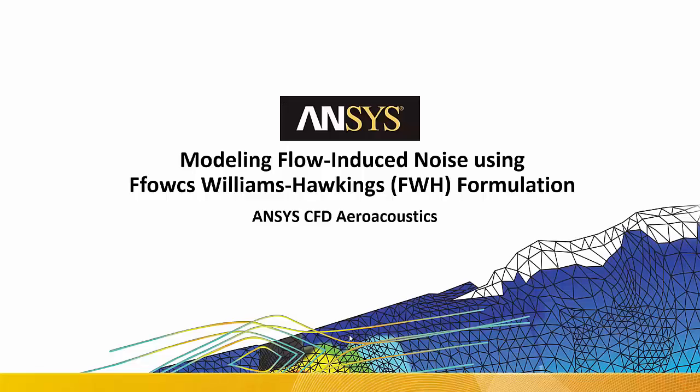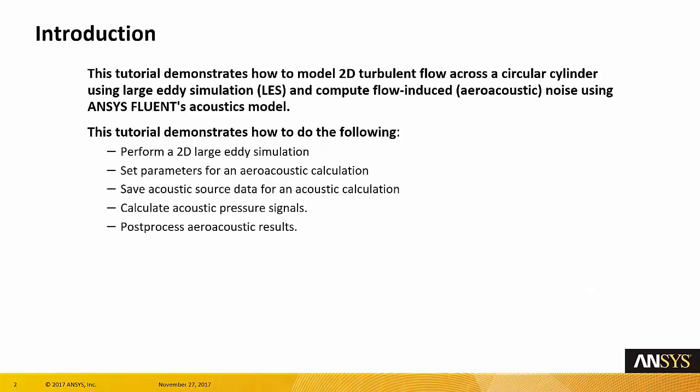Hello, today I would like to talk about modeling flow-induced noise using Ffowcs Williams-Hawkings formulation. In this tutorial, we will demonstrate how to model a 2D turbulent flow across a circular cylinder using LES, and we are going to also compute flow-induced noise using the ANSYS Fluent acoustics model.